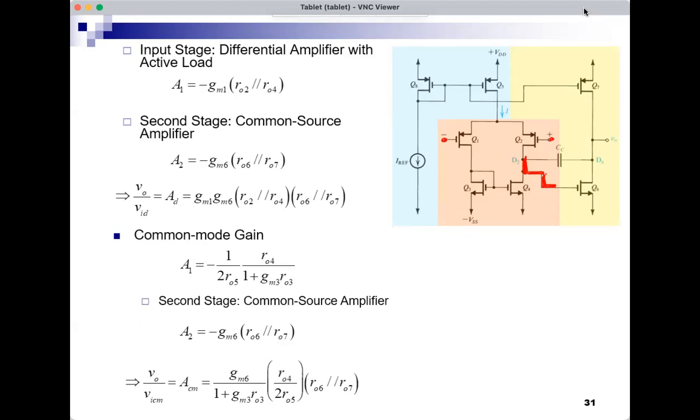So this is ACM for the op amp. And we can, of course, now find CMRR if we want to. CMRR would be 20 log AD over ACM. So that's an expression for CMRR in dB. So that's our op amp, and we now know what AD is for this and ACM. Of course, it's a very simple op amp. It's not ideal. AD is not infinite. ACM is not zero. It's a good start.